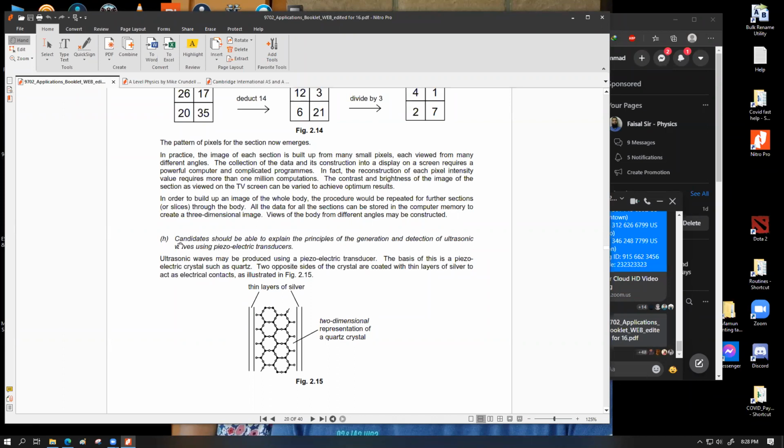We're going to talk through it. It's going to move a certain solenoid coil within a fixed magnetic field, which is going to generate some voltage. This is actually a practical design for a microphone. It is a practical design. But the problem with this design is that there is a limit for how much frequency of sound this device can handle, because